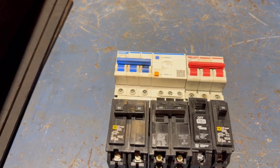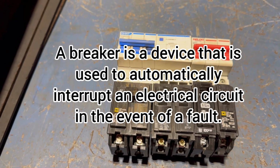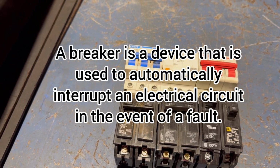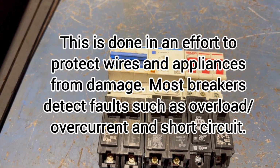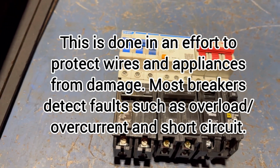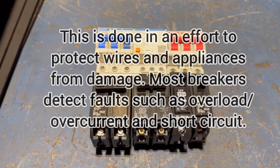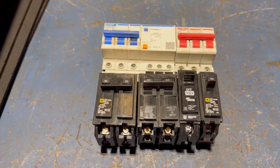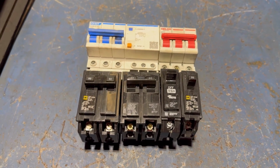So the first thing, what is a breaker? According to my definition, a breaker is a device that is used to automatically interrupt an electrical circuit in the event that there is a fault. This is done in an effort to protect wires and appliances from damage. Most breakers detect faults such as overcurrent or short circuit. There are also some other types of breakers, like the residual current device, that protect against leakage current.